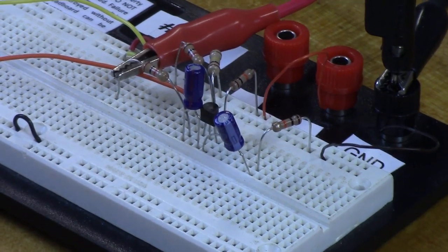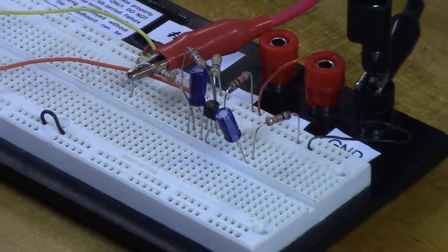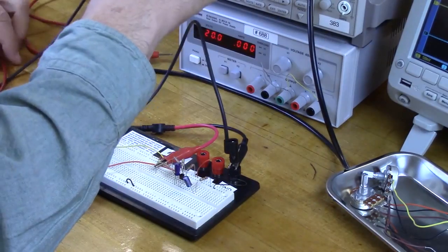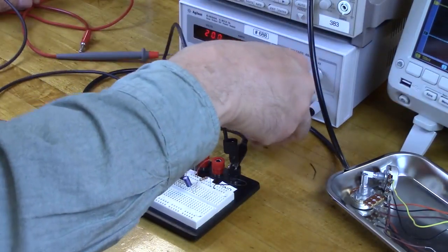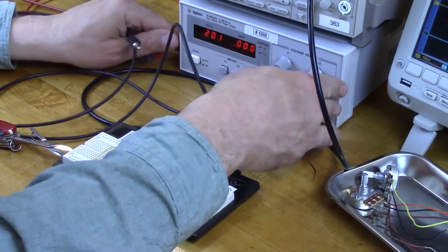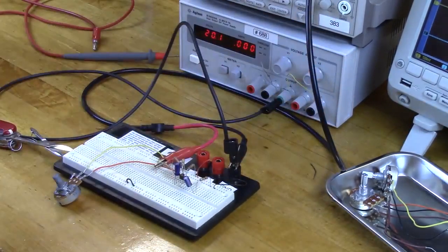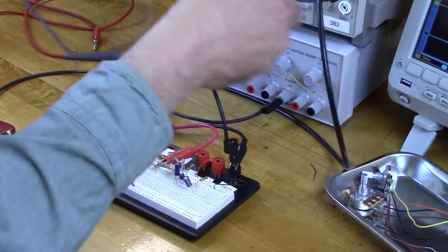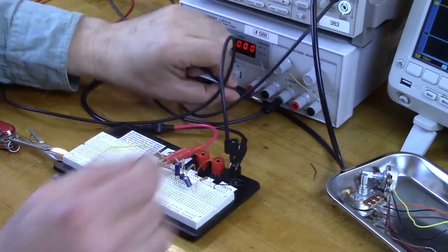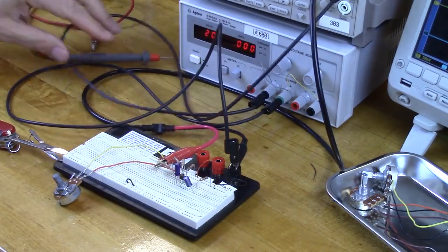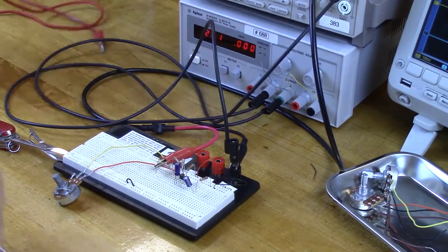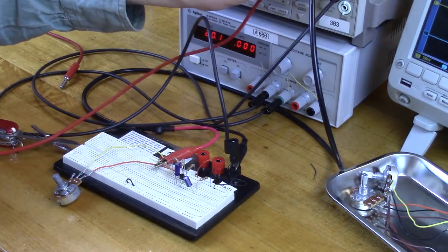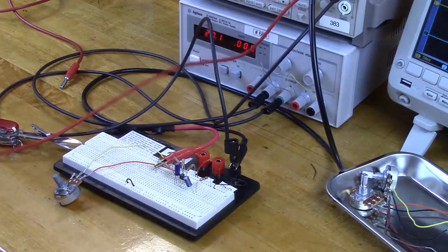We have a ground lead here. We're going to connect, oh, I think we've already got one connected. We can connect that to there. Okay, and then our voltmeter is also going to be measuring everything with respect to ground. So let's connect the negative side of our voltmeter to that same ground point over here. And then for the positive of the voltmeter, we're going to use a probe because we're just taking momentary measurements. So we're going to put this on the plus input up there, like so.